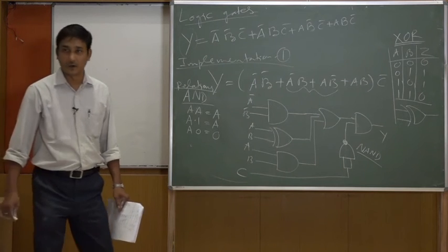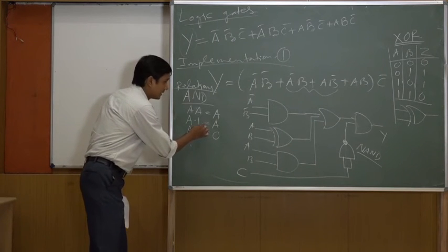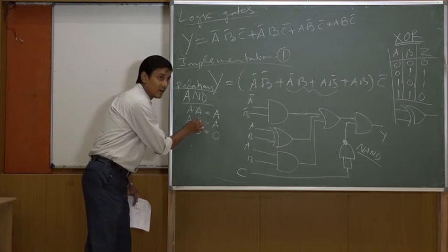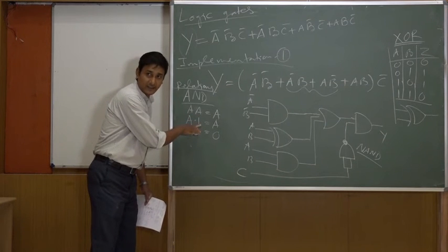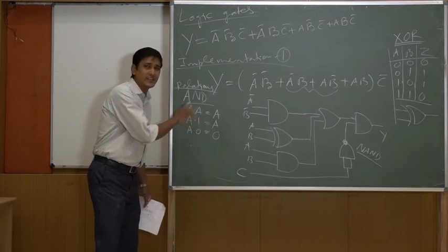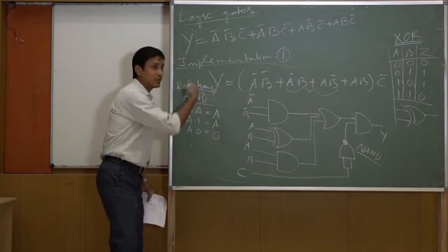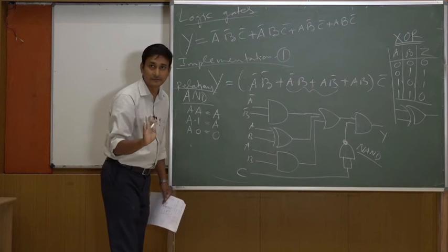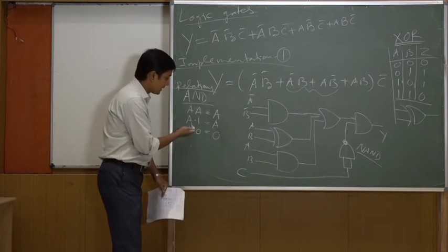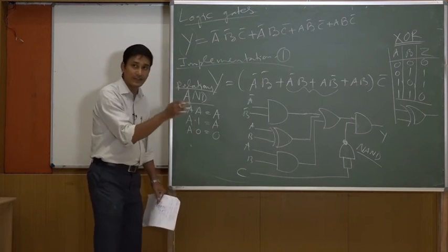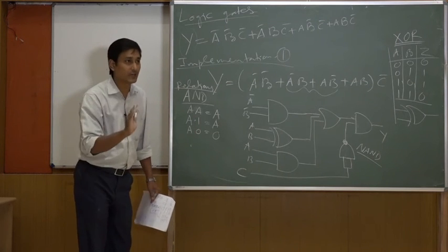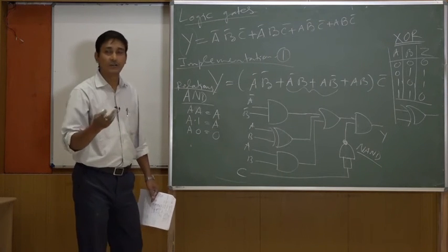Okay. Now, if I put 1 at one input of the AND gate, it does not do anything to the circuit. It replicates the input to the output directly. Can I say it this way? Similarly, the other way: if I put 0 at one terminal, whatever you put at the other input, the output will always be 0.